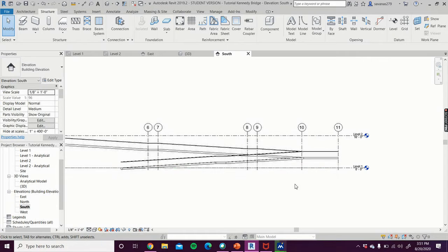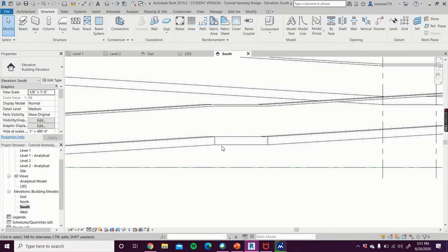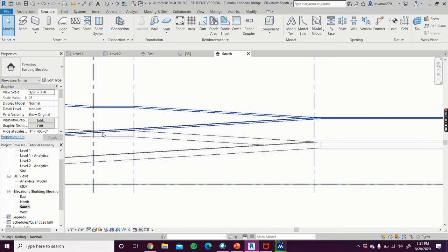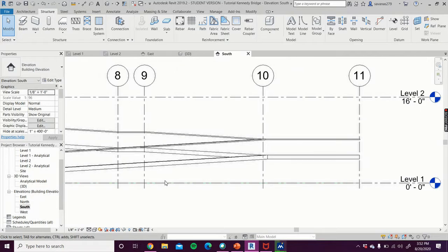Okay, now what I'm going to do is place several elevations that align to the bottom of each flat part. I'm going to be placing one here, and here, and here, and so on. Each of these markers is going to represent the top of one column, because we're going to have one column along each of these flat portions here.